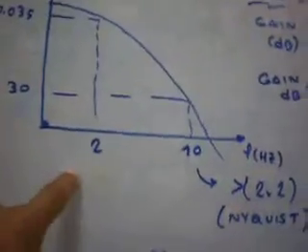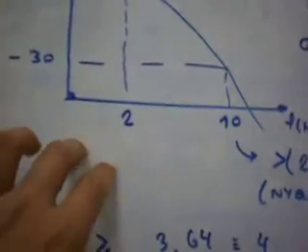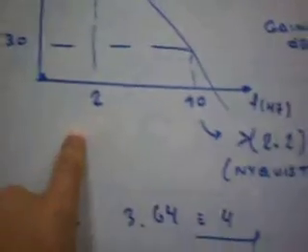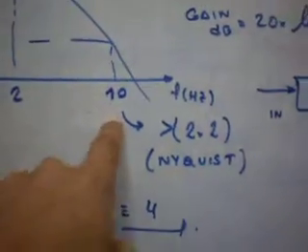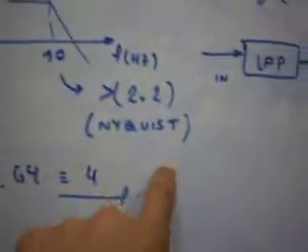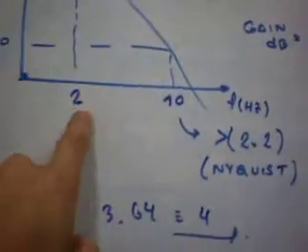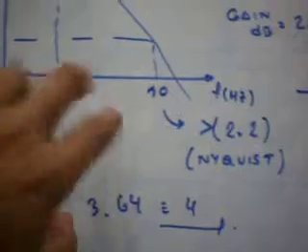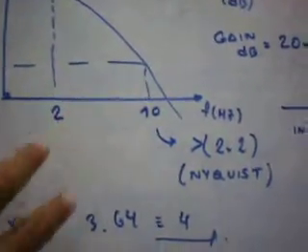I decided this value, and the sampling was 2 hertz, 2 samples per second, just around, and according to Nyquist, I decided to work with more than 2 times this value, to avoid replicas.